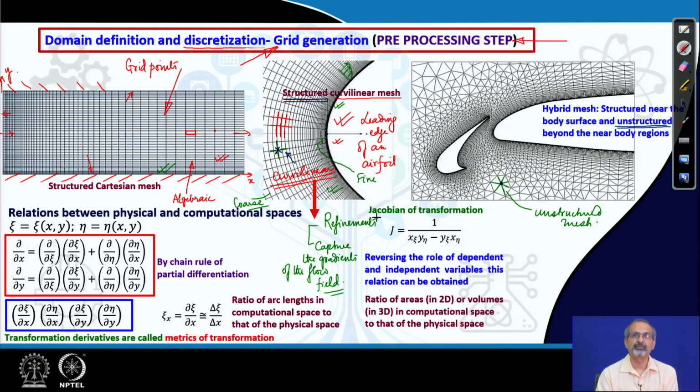That is why a very refined mesh is used for the near surface region. As the Reynolds number increases, especially when you go into turbulent flow regimes, you will see that the small eddies become smaller and smaller as the Reynolds number increases, and therefore, you need to have a more refined mesh in such a situation.